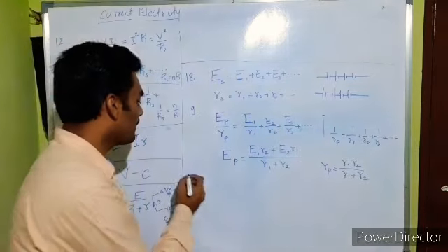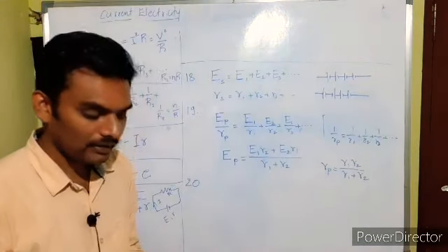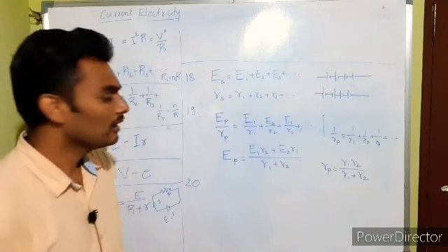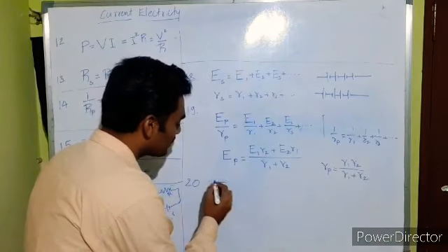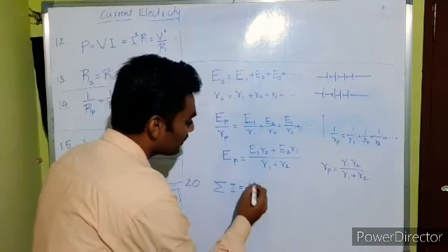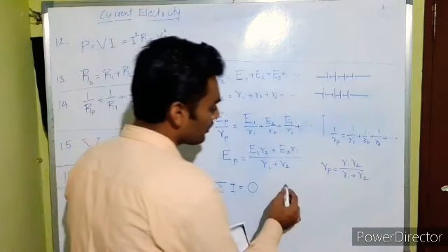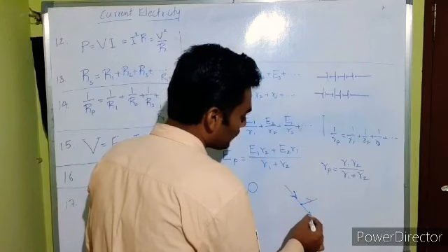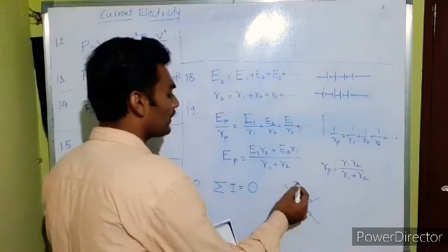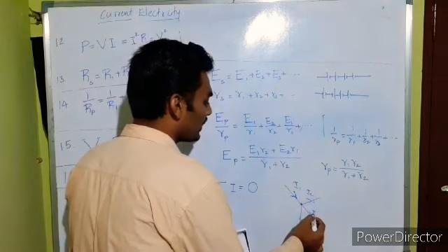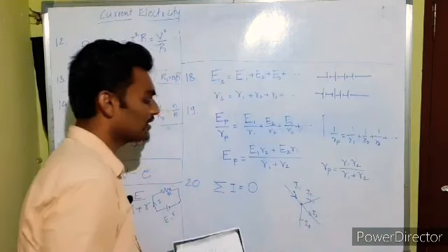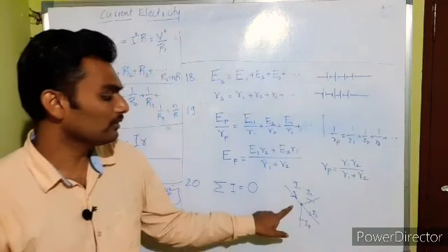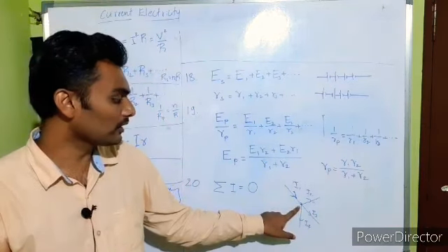That's also fine. Next is about Kirchhoff's law. The first Kirchhoff law, the KCL, Kirchhoff's current law, is given by the summation of currents through a node is equal to 0. Remember the rules. Currents entering the node are taken as positive, currents leaving the node are taken as negative, and hence we add them, and the final sum of all the currents should be equal to 0 for a particular node chosen in the electrical circuit.